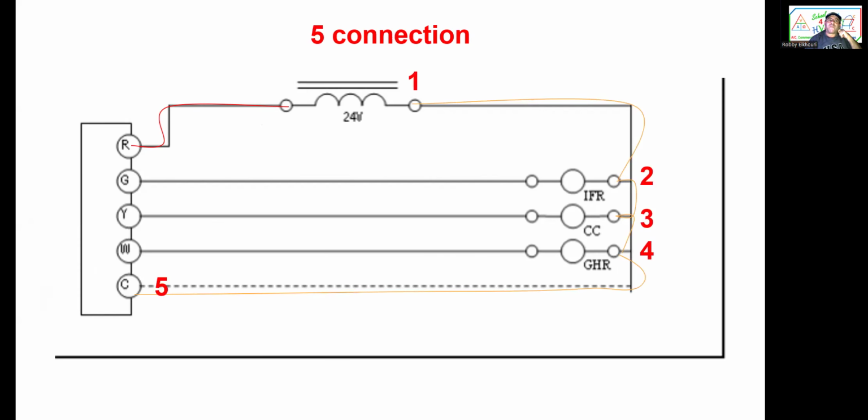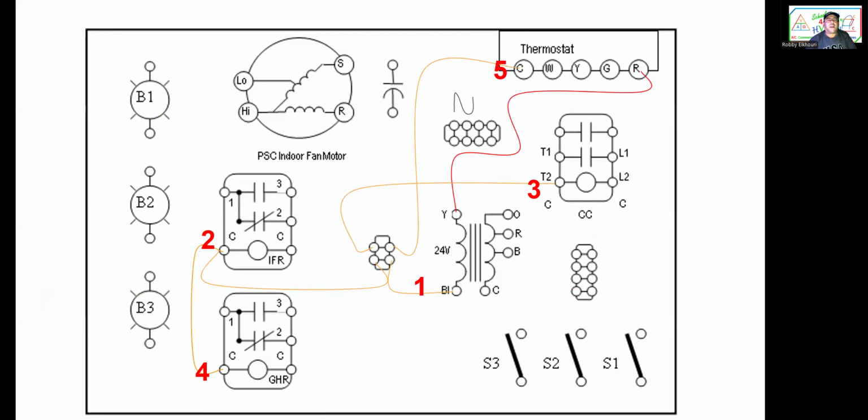Next, we have 5 connections now. This is the secondary. We're gonna do secondary first. This is now S2 or common. We have 1, 2, 3, 4, 5. All right, everything goes to the common. 2 ways of doing it. Either put a terminal board here, and there we go. 5, 4, 3, 2, 1. And everything is on the common.